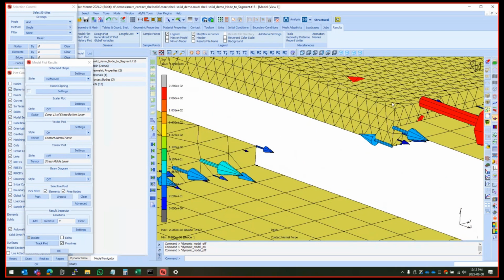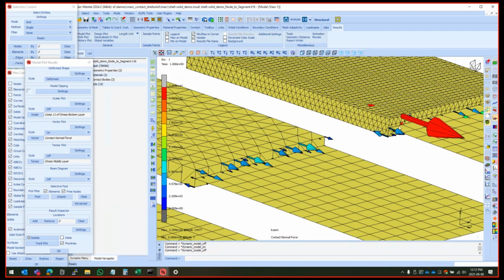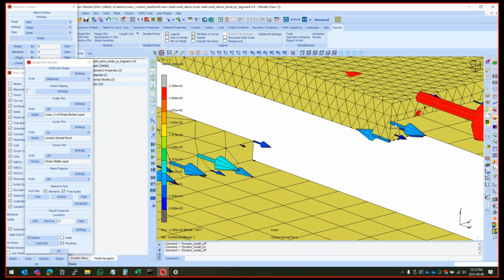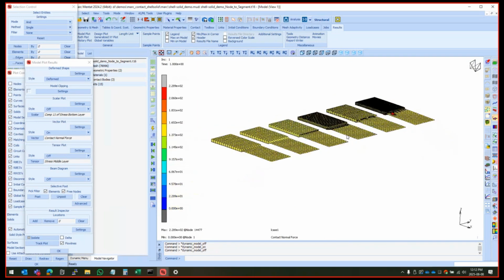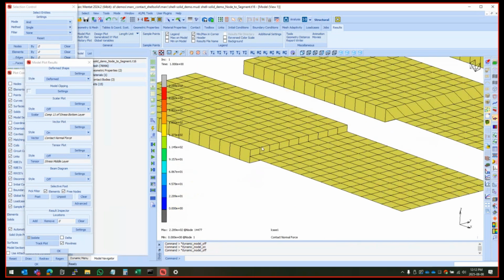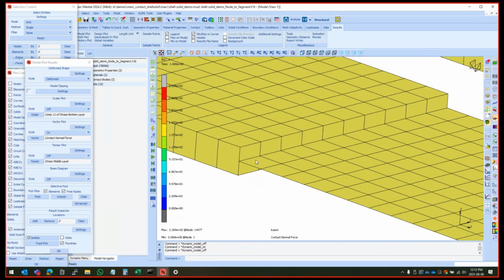And the reason is mostly because firstly, we're only making contact at separate spots, those faces and these faces, but also we effectively only make contact to that closest section. It's as if there was a crack in this face from there to there and there to there, which causes these really weird stresses. Okay, so what we'd rather do, and I've already alluded to this, is I don't want to make contact from this part to that. I'd rather make contact from there to there, except there's nothing on this side.